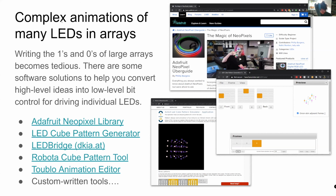So for how do you solve the problem of forward voltage drop for a lot of LEDs, that's a totally good question. It turns out you still power each one separately with their own little circuit, and you deliver power along. So each LED has its own link directly from the power line to the ground line. And then in the Neopixels, they're each attached to power and ground, and then there's a data pin running along them. In the case of these LED cubes, you have arrays and they're blinking on and off in really weird fashions so that you can cleverly solve that problem.